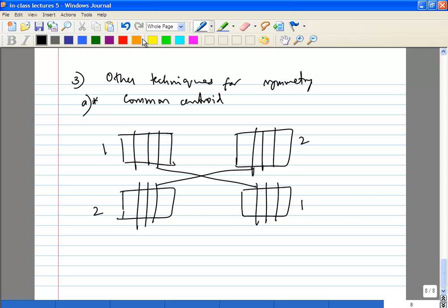So let's call this A. Obviously other very basic things: orientation. Obviously, if you want to match 2 transistors, let's say one was like this, you're not going to make the other like this, that's for sure. That's very stupid, right? So you're definitely going to make sure they have the same orientation.